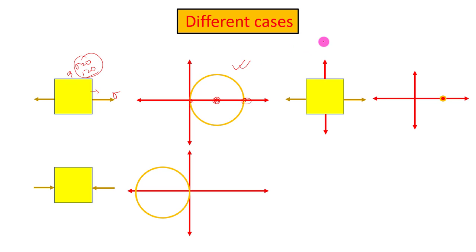Next case is that if we take a case of biaxial case, in which your sigma x is equal to sigma y. If we look at this face, this represents a point on the horizontal axis because it's tensile in nature. Similarly, this sigma y also represents the same point on the horizontal axis. So what's the physical significance? Because this is a special case, it doesn't represent a Mohr circle.